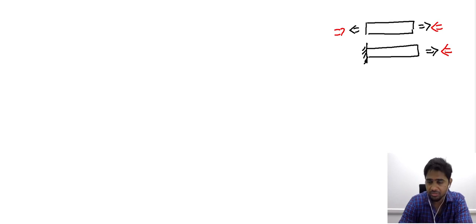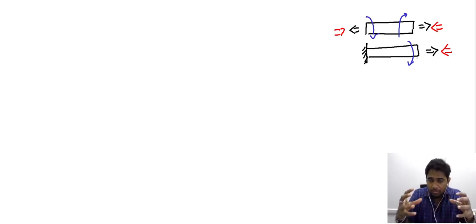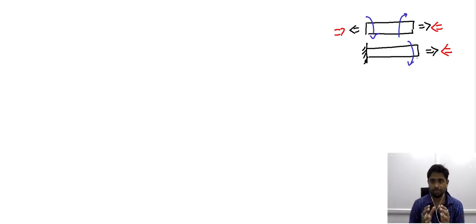In the same manner, it is also possible for us to introduce torsion loading. So if you have an equipment and that equipment handles the sample in a specific way, like we have seen here, particularly if it is possible for us to handle the sample along its length, then it is possible in that equipment to impose tensile load, compressive load, and also torsion load.